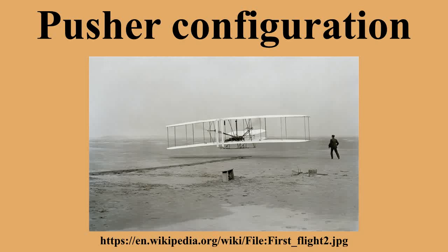Although the vast majority of propeller-driven aircraft continue to use a tractor configuration, there has been in recent years something of a revival of interest in pusher designs. In light home-built aircraft such as Burt Rutan's canard designs since 1975, ultralights such as the Quad City Challenger, flexwings, paramotors, powered parachutes, and autogyros. The configuration is also often used for unmanned aerial vehicles due to requirements for a forward fuselage free of any engine interference.